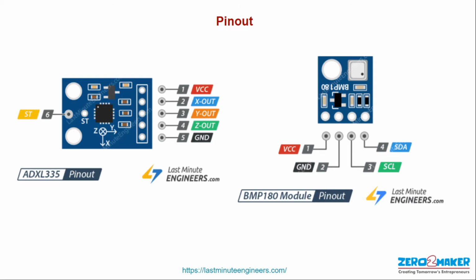So here there are 3 pins as an output which will go to Arduino. There is one pin 6 which is the state pin which will also go to Arduino. Now the second sensor is the pressure sensor, atmospheric pressure sensor. Here you can see there is SDA and SCL. That is one more kind of I2C communication which is much simpler, not at all hard, but that also goes to Arduino. And this is how you will understand, every sensor will have different pins, but you will easily be able to identify using Google how to connect where. So I just wanted to clear that idea.